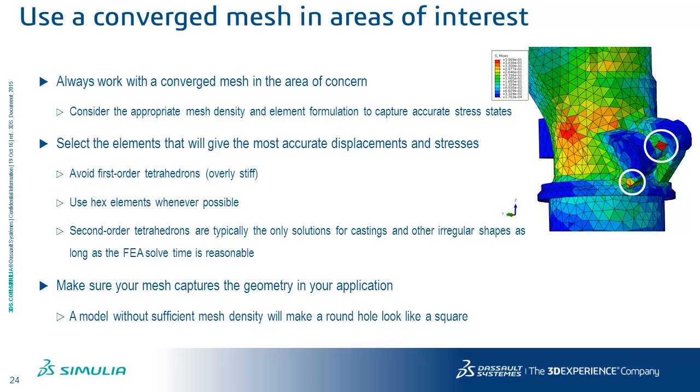Once you get the convergent mesh, which means you don't have any serious jump in the stresses and strains between neighboring elements, then go through the fatigue calculation afterwards. So that may be one of the important recommendations regarding the FEA concern when you do the fatigue calculation.